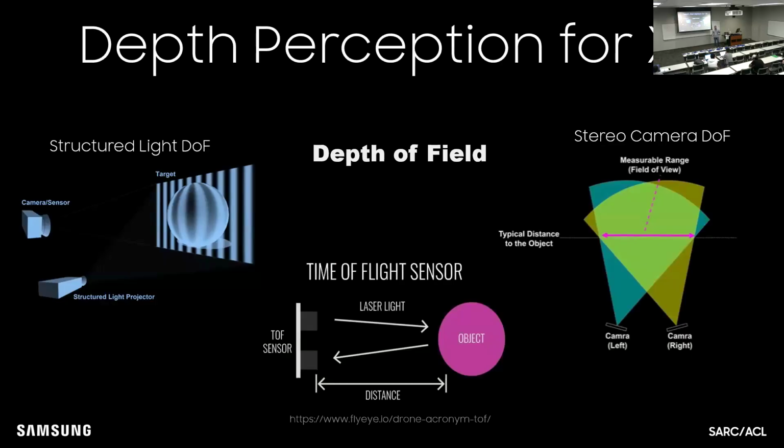One of the most important parts of that sensor fusion, which is what they call it when you have a bunch of different sensors coming in and trying to munge the data together, is depth perception. You can do it. These are just 3 typical ways of doing it. Structured light: you put some kind of IR field on something, and if there's something in front of it, those IR lines or patterns or hash marks are going to deform, and then you can tell the depth by that deformation.